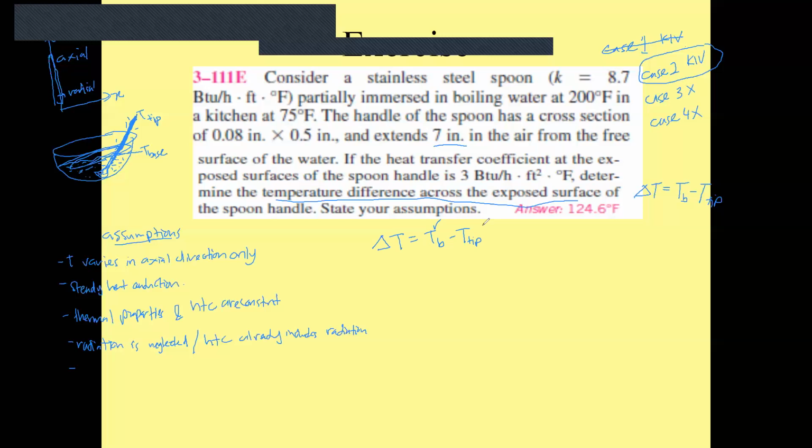So how do you find the temperature at the tip? It is from the temperature profile. Okay, so you look back in the slide and look for the second case, and you will find that the temperature profile for the adiabatic fin tip is given by this.